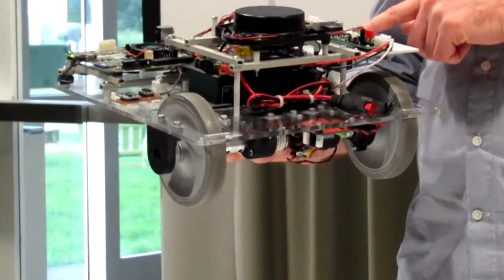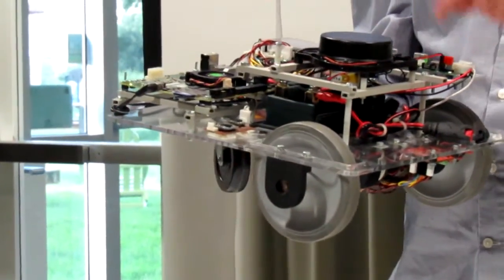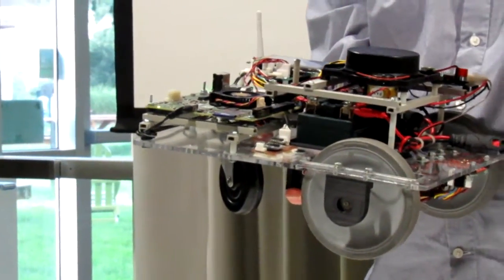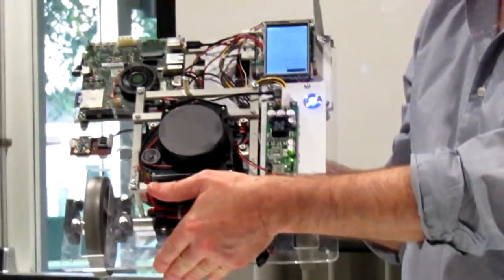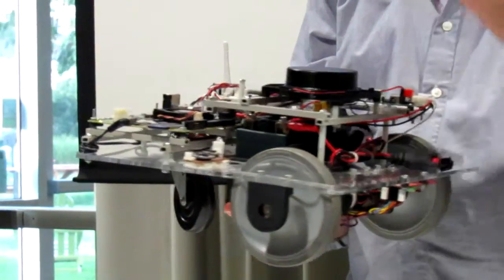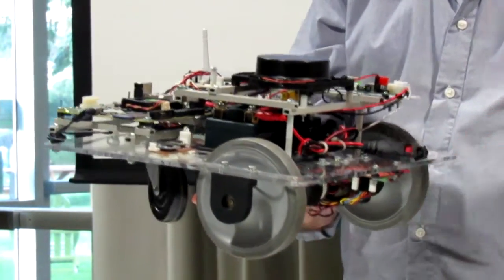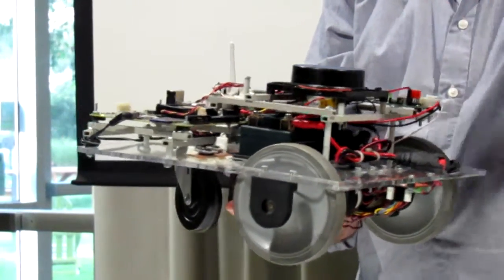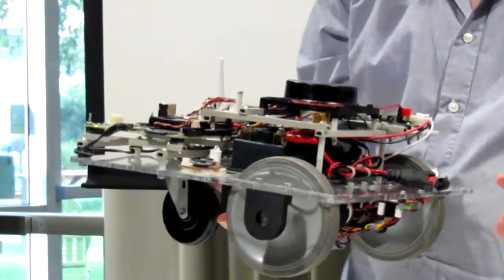It also works as an automotive power supply, so it has an output that will control the power switch on the Jetson TK1 on there. When you turn this on, it'll send a power on message to the Jetson, and when you hit the off button, it doesn't turn off immediately, it sends a shutdown signal and waits for the Jetson to shut down, so it's really nice.